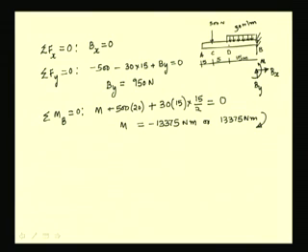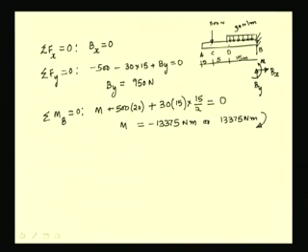In order to construct the shear force and bending moment diagrams, we can take sections for which the loading patterns are similar, because the behavior of the shear force and bending moment curves will be constant or the same for a portion where there is no change in the loading behavior.